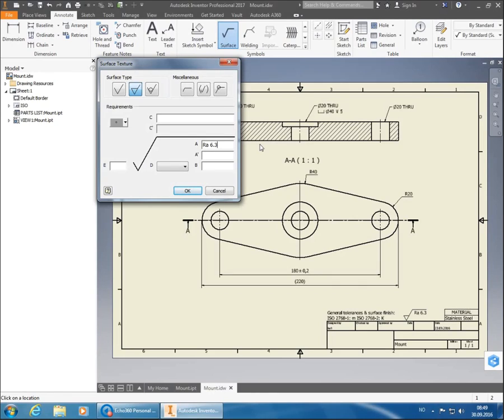So, if like in the submission, you don't know anything about the general tolerances or surface finish, I would advise to choose the medium tolerances and choose this surface finish, the 6.3. If you have a smaller number here, so a finer surface finish, it means that the machining shop will have to run their machines slower in order to manage to create such a fine surface. But with 6.3, they can use their normal, regular production speed. And that is usually good enough.